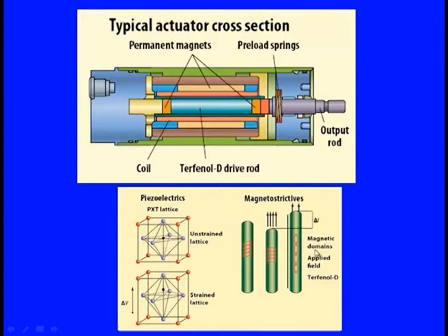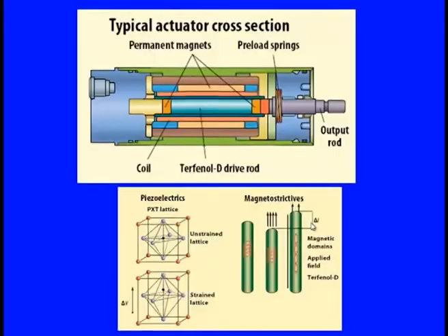So, this is my delta L, and then I can get what exactly the strain is. These Terfenol-D rods can be straightaway put here, and we can see a clear change even at the micro strain, the real structure, when the entire lattice structure is being strained according to the magnetic field applied there.